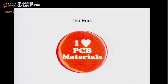Yeah, so you can look for lots of different things. The main high-level thing is looking at the actual electrical design, what's connected to what. That could possibly be the state of pull-up resistors, or the state of current system, or maybe configuration resistors in there. Some boards actually have components built into layers, which I don't discuss here, but higher-end boards can have resistors and capacitors built in, so maybe you'll be able to identify things there.